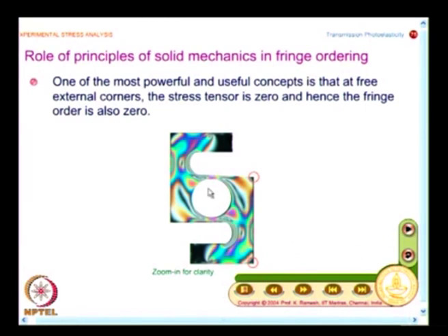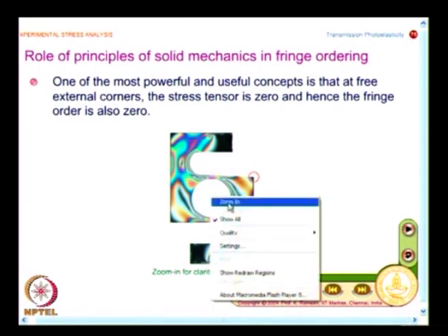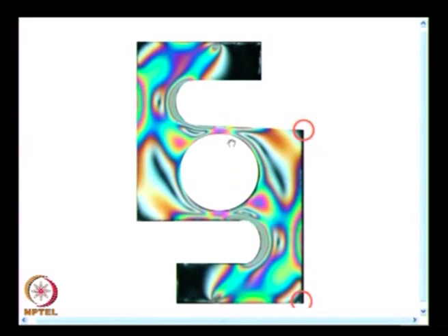I have this here, and I have this fringe field, and this is used in many popular load cell designs. This is a spring element, and they would have strain gauges put inside the boundary of the hole, and this also can be hermetically sealed. And what I have here is, this is subject to compression along this direction and this direction, that is what you see here, and there is no load applied here.